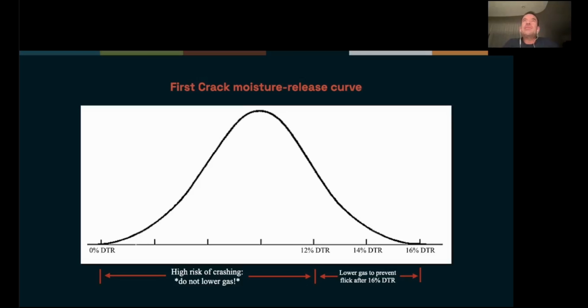Does the steam that releases during first crack increase the drum temperature? No. Oh, lower the drum temperature. Potentially, but probably insignificantly. The moisture coming out is going to have a big effect on the surfaces of the beans and the ability of the hot air to reach the beans. But I don't believe it has a significant effect on the surface temperature of the drum, since the drum is so heavy and so hot, it's not going to get affected much by a little bit of moisture. Any other related questions?